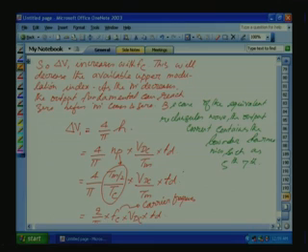So, in many high performance drive applications, when we require near zero speed operation, the dead time effect has to be compensated. For dead time compensation, we require the direction of the current. So, a typical way to reduce this, we can see in the next slide.